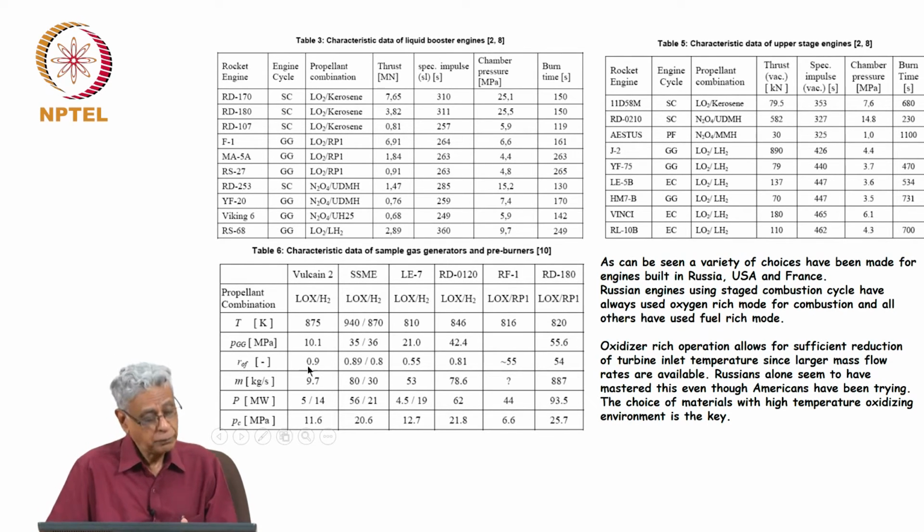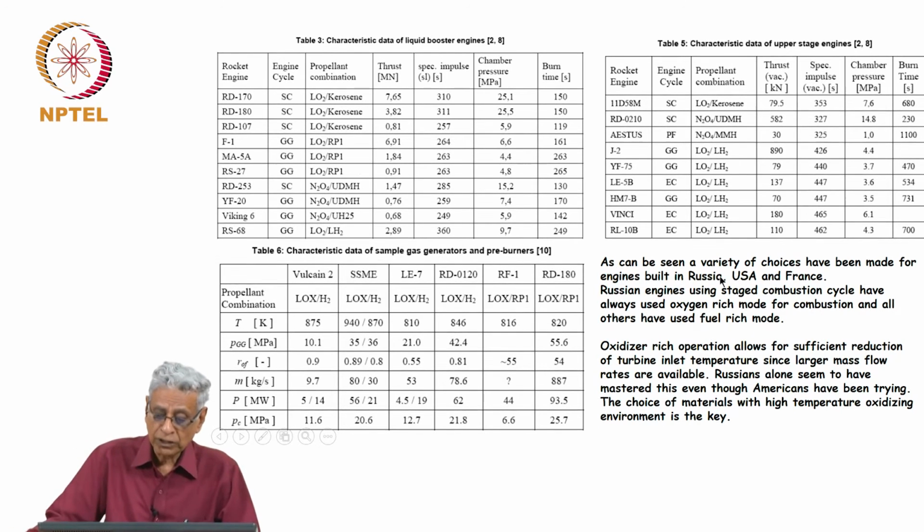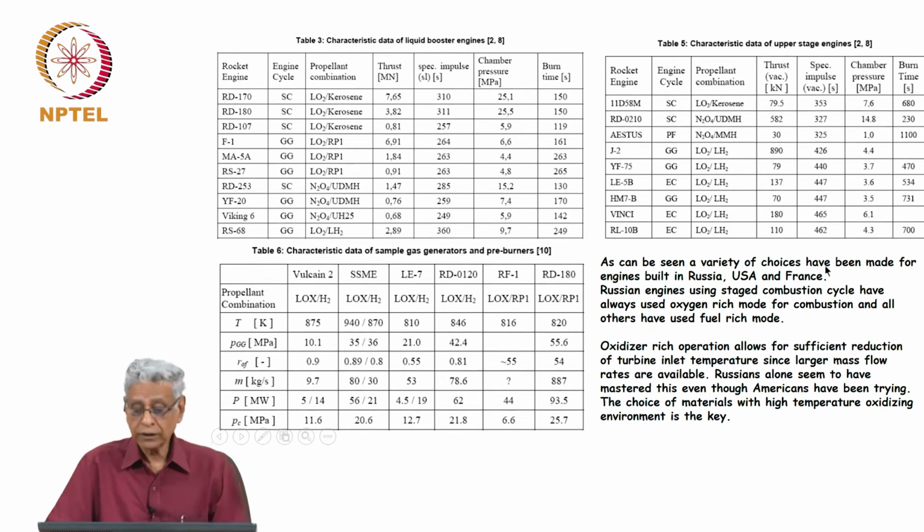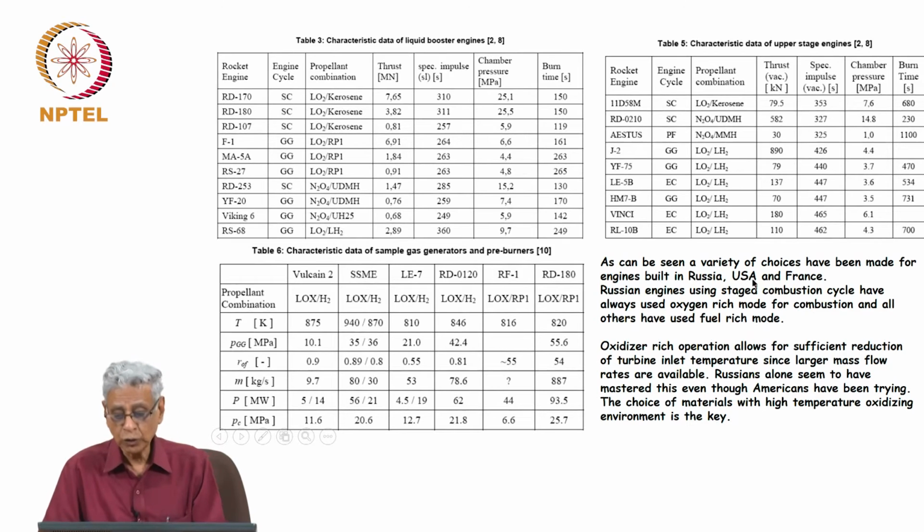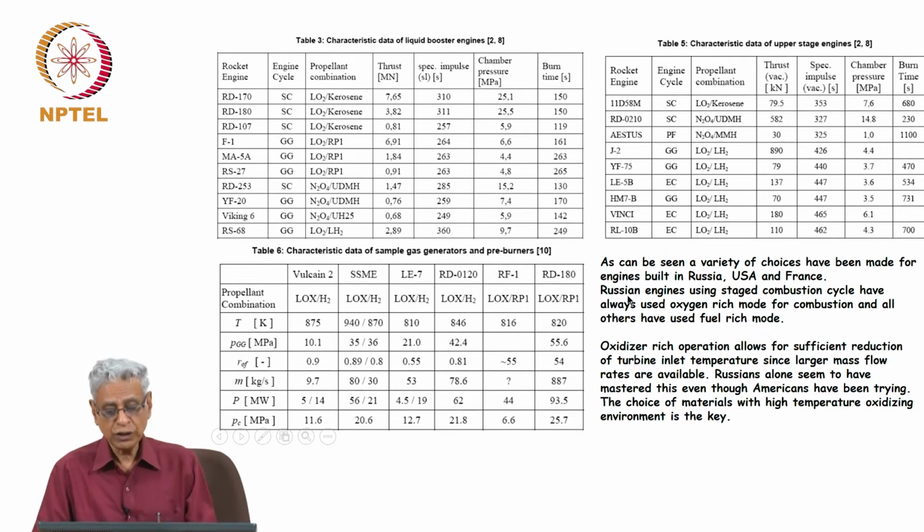It can be fuel rich, as is usually the case, or oxidizer rich, and this is a speciality of Russian engines. That is what I have written here. As can be seen, a variety of choices have been made for engines built in Russia, USA and France. Russian engines that use staged combustion cycle have always used the oxygen rich mode for combustion, and all others have used fuel rich mode.